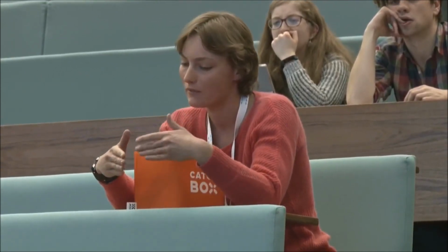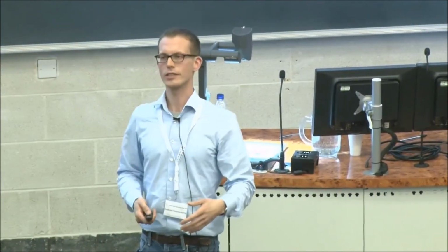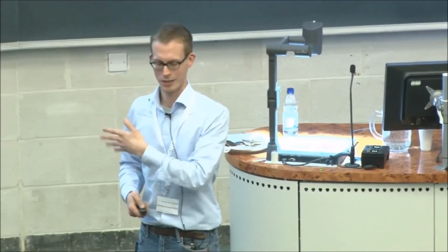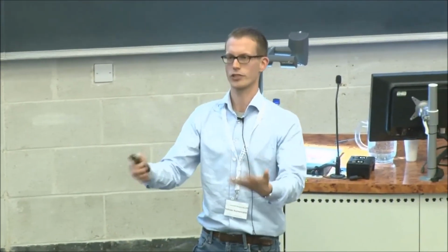Henning again. One question about the optomechanical cavity on a chip you showed. If you implement this on a chip, isn't there a problem with noise feeding back onto other systems you have on the chip? Because if you move the mirror mechanically, I would expect that it also leads to decoherence in other systems which can be connected to this on the chip. Yes, there's definitely coupling. There's finite decoherence in the problem, and so the mechanical motion is damped. It is surprisingly little damped, and it can oscillate for actually, the typical quality factors are in the 10,000s, 100,000s, so it's pretty well isolated. And that takes everything into account. That's like the effective thing you actually see in ring down.